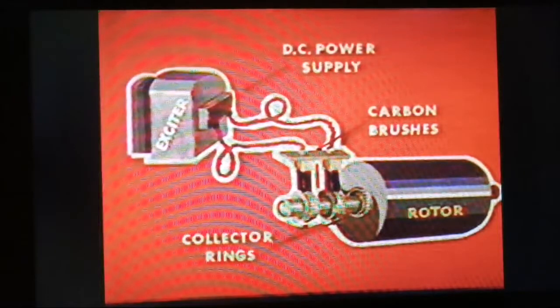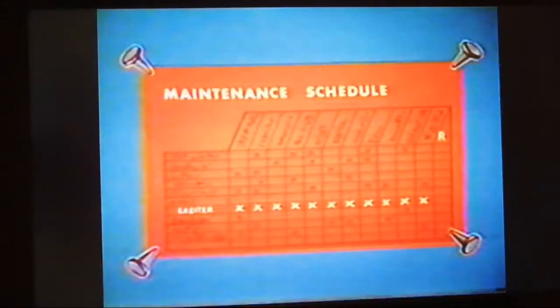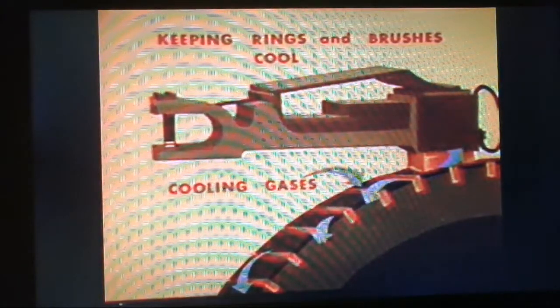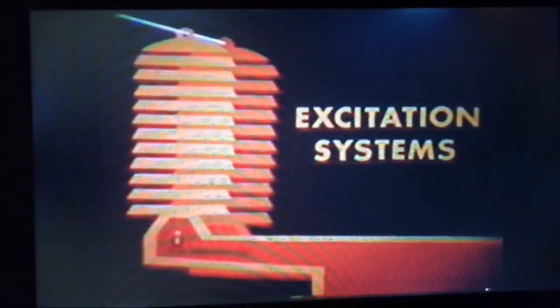Brushes on both commutator rings or slip rings must be kept clean, free of oils and grease, or any foreign bodies which would reduce the easy flow of high currents. The spring pressure which holds the carbon must be properly set and maintained. Cooling is important also in the brush area. Grooves in the rings permit cooling gases to circulate under the brushes. Various other methods are employed to keep the rings, brushes, and brush rigging from overheating under high current loads. The operation, control, and maintenance of the exciter and its related equipment will be developed in a later lesson.